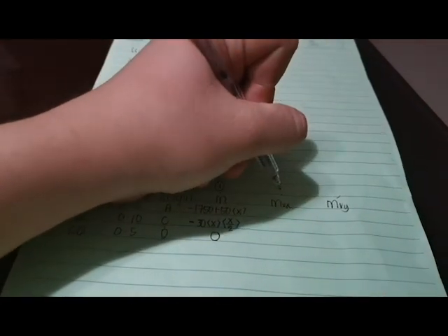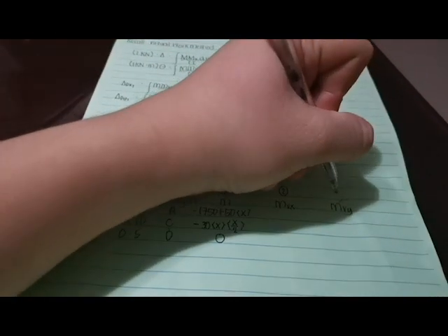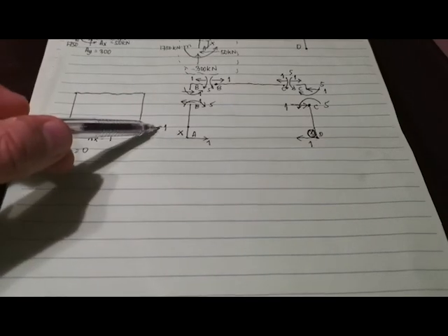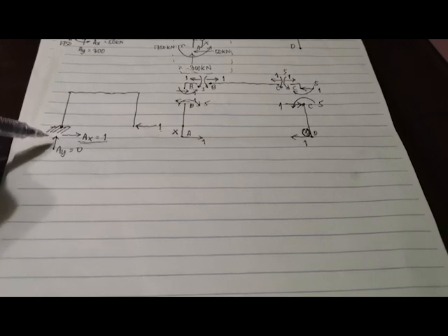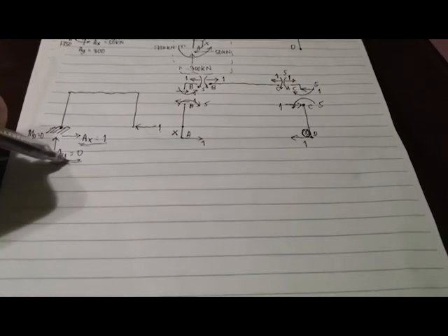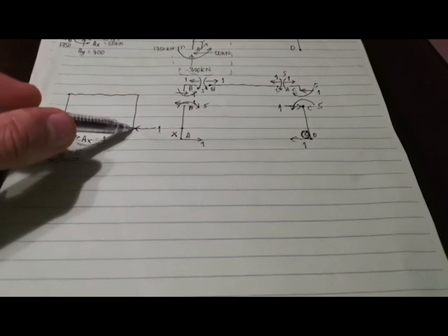So let's proceed with your frame number 2 and frame number 3. Let's proceed with frame number 2. We determine the reactions first. So this is your horizontal unit load. If we do summation of forces X, we will be able to know that your AX is just the opposite of this unit load, which is also equal to 1. If we do summation of forces Y, AY is equal to 0. If we do summation of moment at A, your unit load here will pass through point A, so therefore your MA is equal to 0.